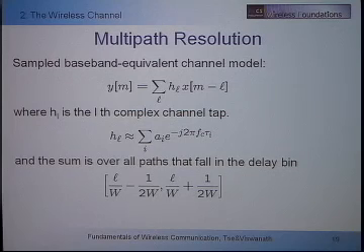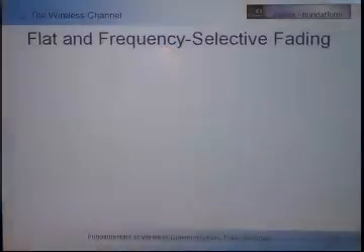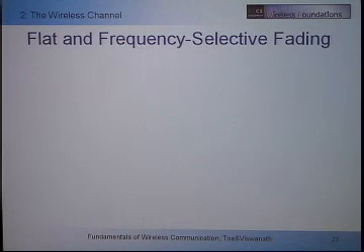This is rather basic, a lot of people may think, but it will become useful when we talk about MIMO tomorrow. Because in MIMO, which is a more complicated problem, I will essentially apply the same strategy to think about MIMO communication. Any questions? All right. And that's a very important point: if your bandwidth is W, the resolution of multipath will be up to delay of size 1/W.